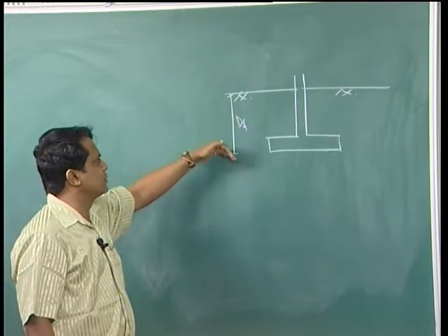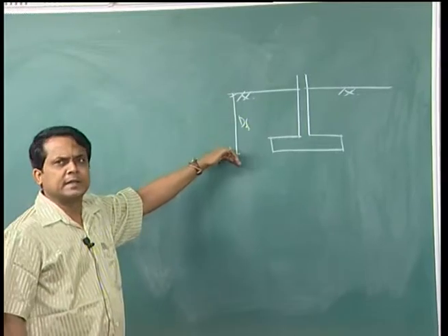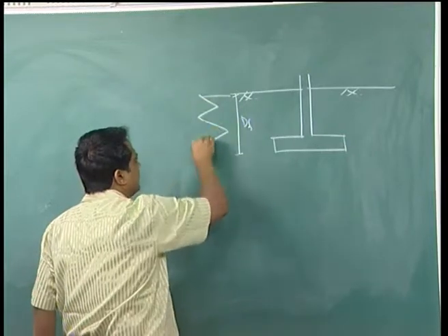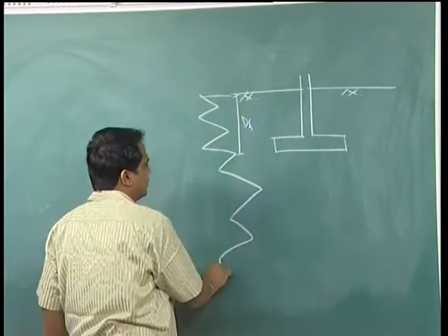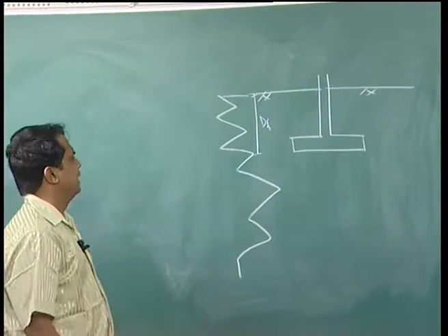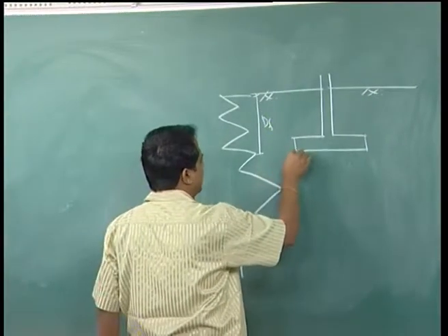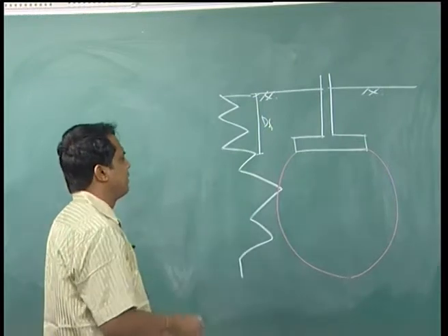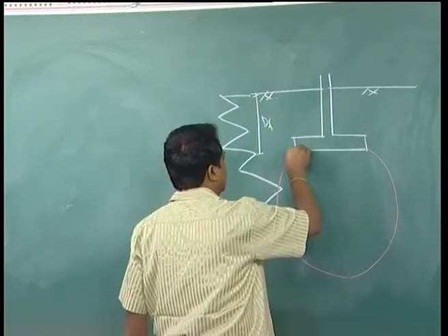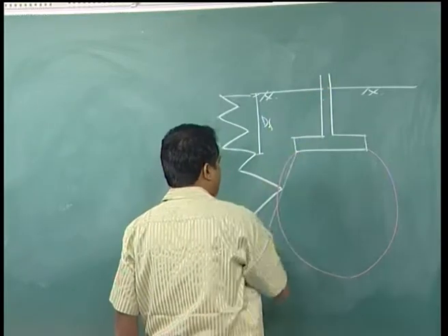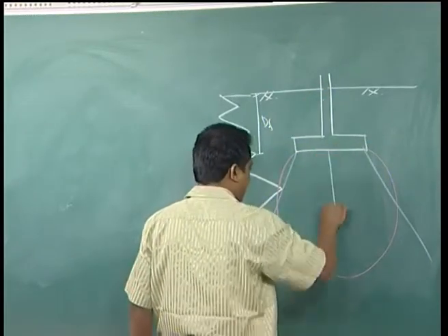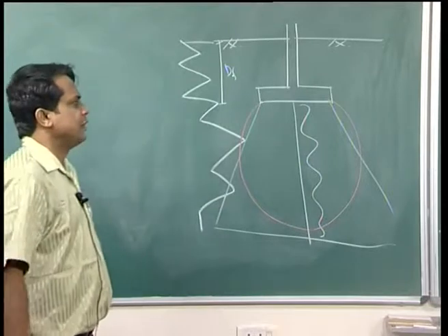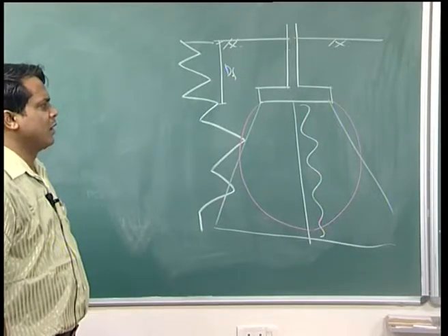With this penetration you will find a layer below this footing, because below this footing is your pressure bulb involvement. That means this is the transfer of load, the transfer of stress below this footing. You have to find it out in such a way that below this footing, at this depth, the soil strata should be hard or maybe strong.